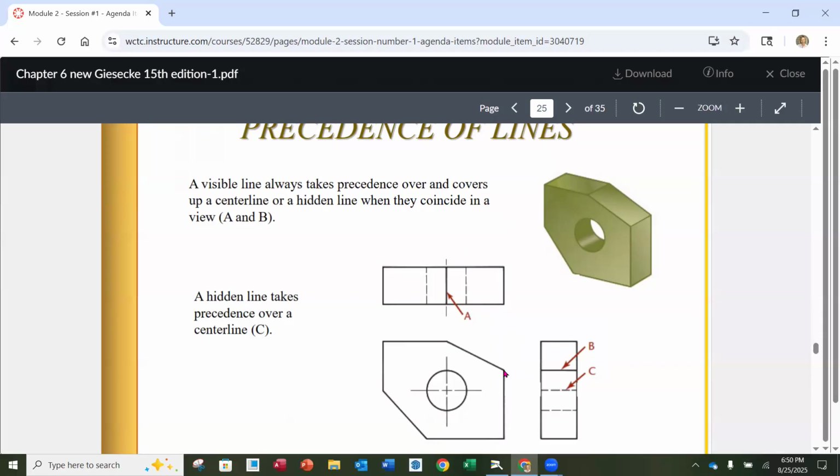And that's what we see here. We see B. So B is right here. If we go left, left, left, it would be a hidden line for the top of the hole. We do not show B as a hidden line. We show it only as the closest edge because we're going to see the edge first. Okay, so it is an edge.